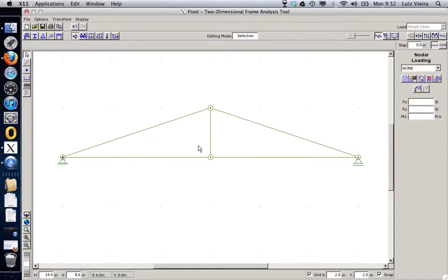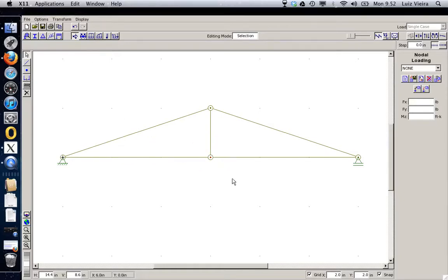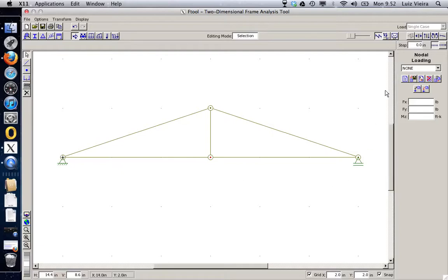So the machine will actually apply a force on the bottom chord of your truss. And this force will be of 120 pounds maximum. The machine can't apply more than that. So let's create this force. I'll create a new force, 120, and then I'm going to apply. This force is a force in Y of minus 120. Why minus? It's because it's going down. So I have the force there. And this is my truss. My truss is ready, we are ready to actually get all the forces.